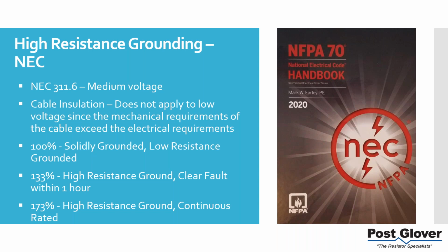But one thing I do want to mention on medium voltage cable installation, all your phase cables are going to have to be higher rated. I think it gets missed sometimes. If you want to use a medium voltage high resistance ground system, you're going to need to potentially use elevated insulation of cable.